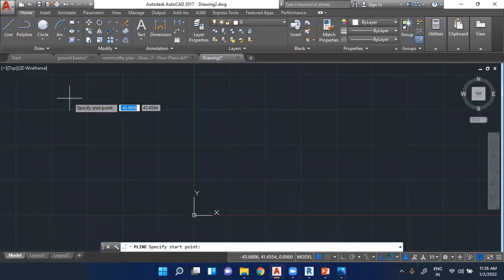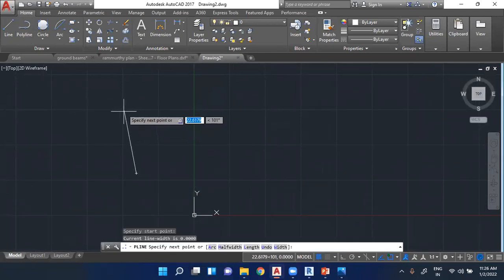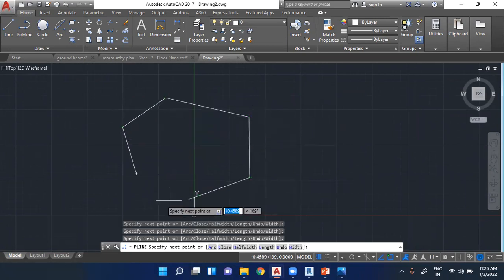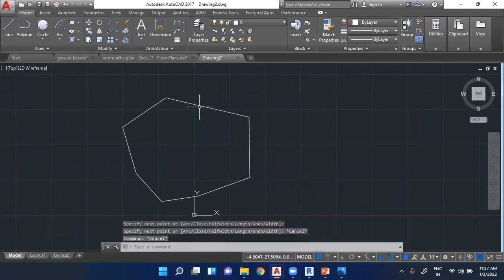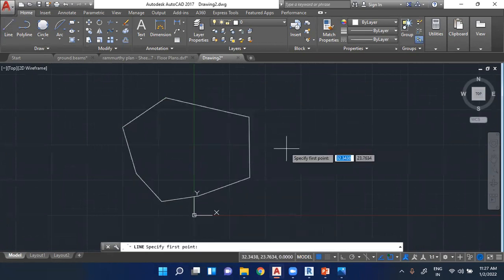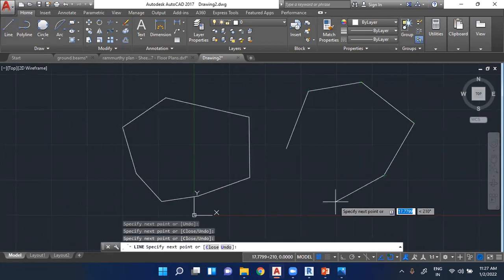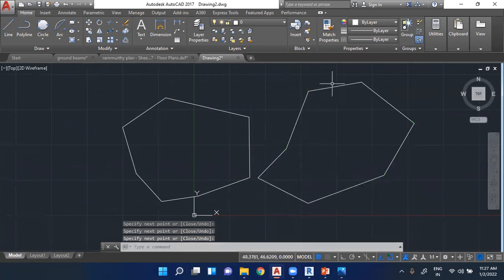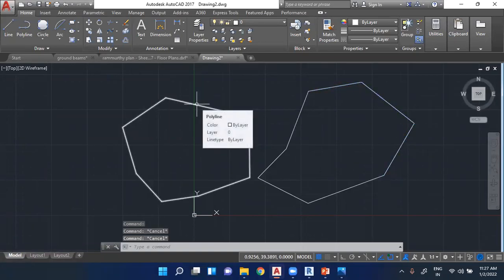And there is an option of polyline here. Let's just click 2-3 points here so that you can understand. In line, line is just individual segments. After clicking at every point with the line option, it creates individual segments of lines. But in the polyline, it creates a grouped section of lines. As you can see here, when I click on a line, it selects one line at a time. But the line plotted using polyline is selected as a whole.